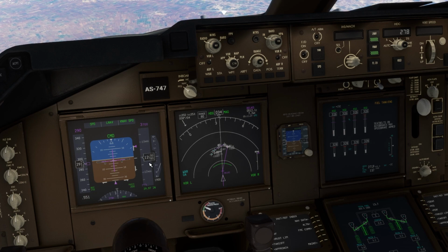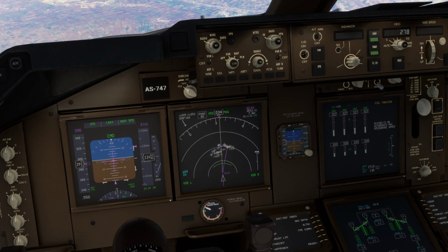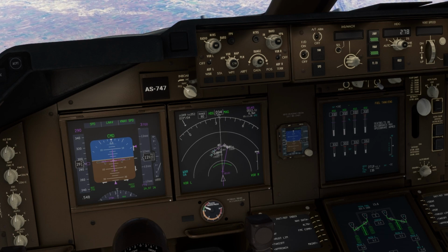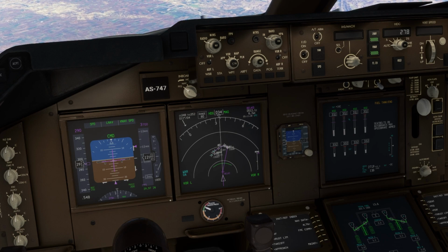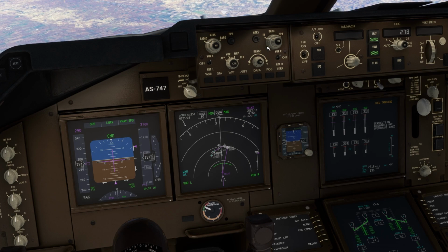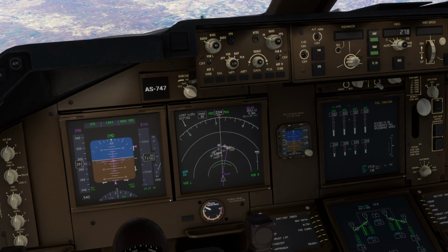Now the altimeter is actually adjusted. The plane calculates its altitude based on the barometric pressure which is outside. So that's why you have to do it. Once you reach the transition altitude, you have to change the barometric pressure. Before that transition altitude, it is always standard. So to use standard, you press standard, and once you want to set it manually, you have to then